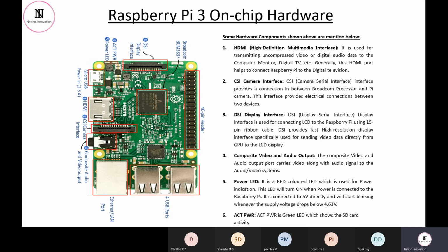In case we want external analog devices to take analog inputs, we connect an Arduino Uno or a Nano with an analog sensor and send that value directly to the Raspberry Pi board, and the rest is done. The problem of analog functionality is removed. This is how we can use the common functionality of simple devices and club them together.